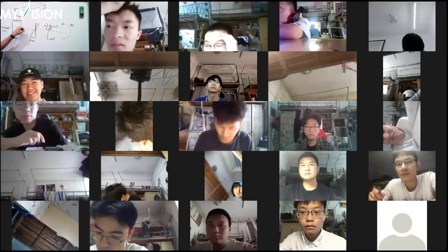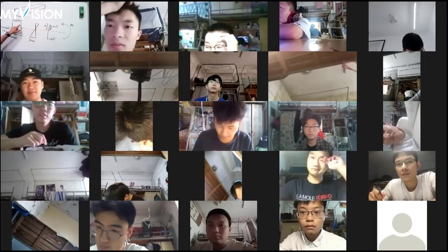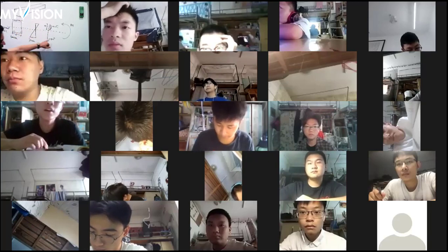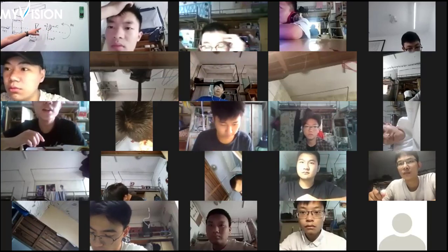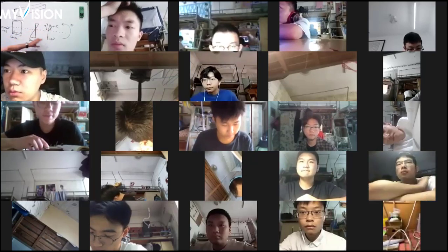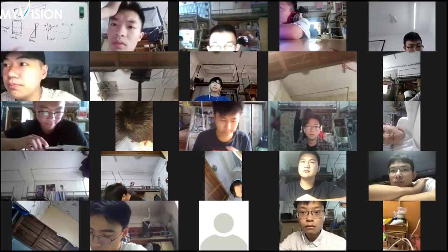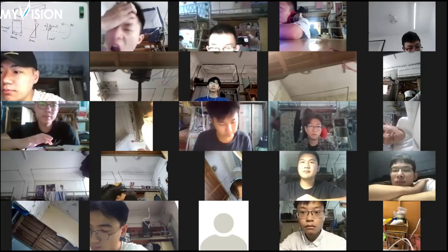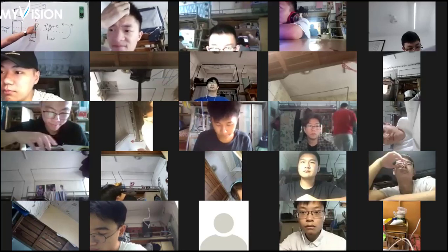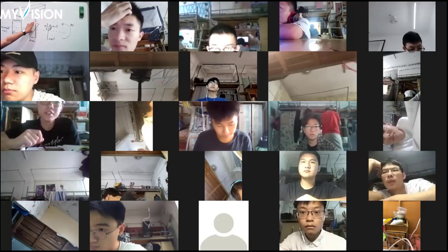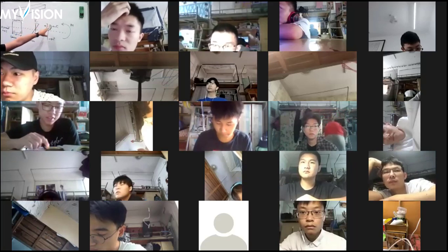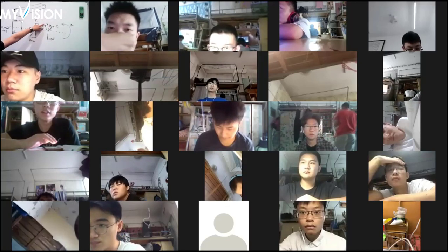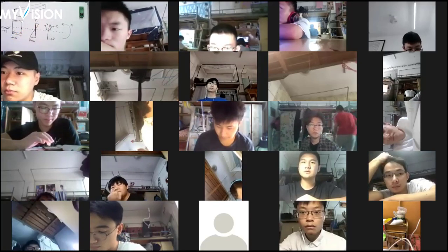First, we are moving towards the stresses. Compression part will generate compression force. Tension part will generate tension force. Because of this compression force and tension force, this strain is generated, which we denote by epsilon. Because of these forces, a kind of moment will be generated, being clockwise. The depth of this compression part will be equal to small a.